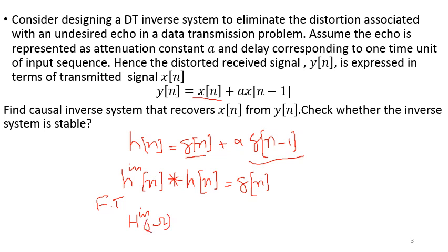And because convolution in time domain becomes multiplication in frequency domain, we generally do not put any sign, so that means it is multiplication. So this will be H of j omega, and this is equal to, and you understand the Fourier transform of impulse is 1, right?